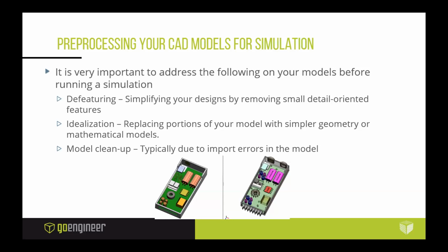Whether that's making a copy of the assembly or the model in general, I recommend doing a Pack and Go. Who here uses Pack and Go? Yes, perfect. So do a Pack and Go. Use a prefix or a suffix to have unique file names, so it's completely detached from the original set of files. And then for that one, go nuts. Go in and defeature, suppress things, or even delete if you need to, but simplify the model in that way.